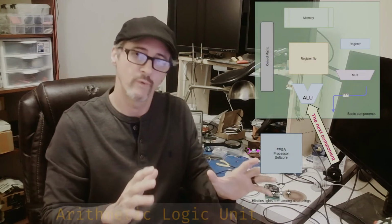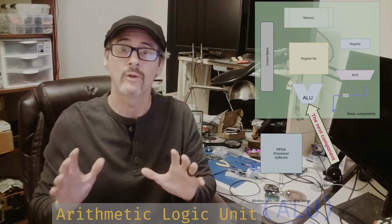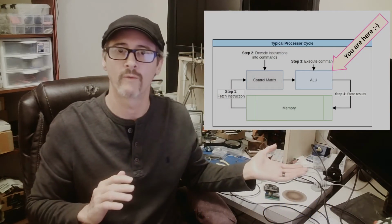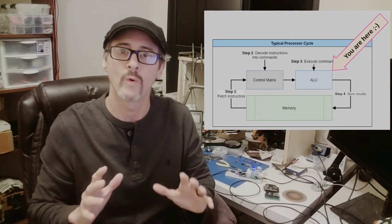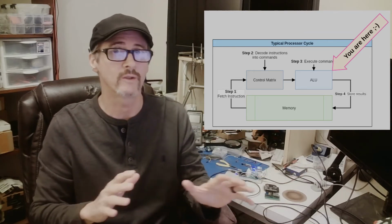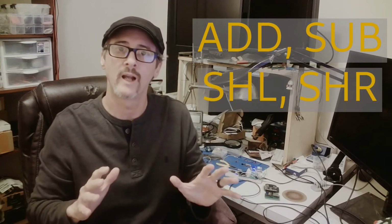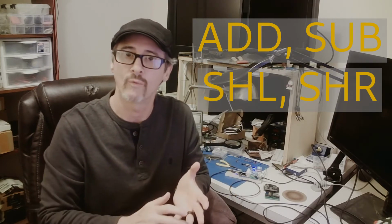In this episode, we return to building implementations and build the core component of our processor, the Arithmetic Logic Unit, the ALU. This is sometimes seen as the execution part of a processor because it performs calculations that influence the flow of data. In our design, we are going to combine both the arithmetic, the add and subtract, with the logical, the shift left and the shift right, into a single module.